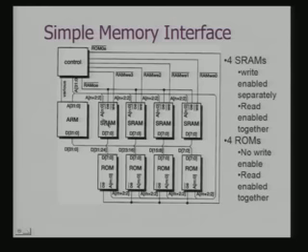The reason the last 2 bits are not being used is that if these are all 32-bit word data, and there are byte addresses, they have to be located at a 32-bit boundary, so the last 2 bits become redundant. And this is a common data bus to which both RAMs are connected. So effectively it is in terms of 32 bits.